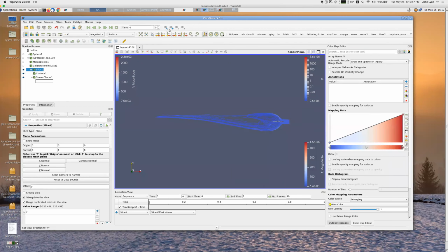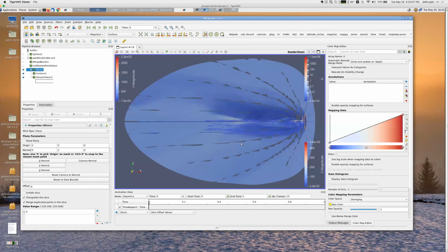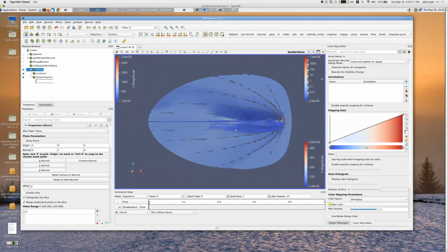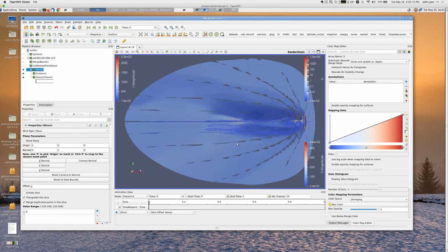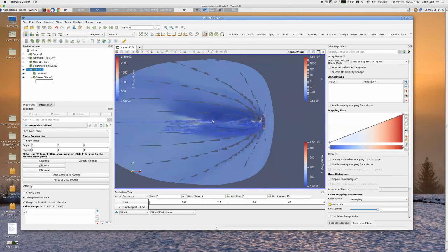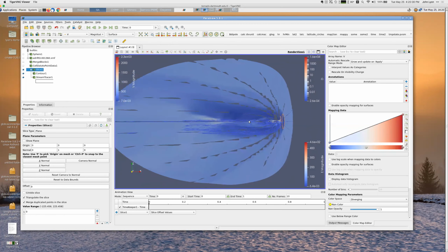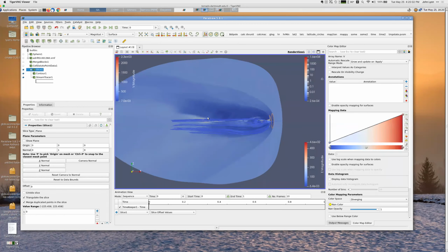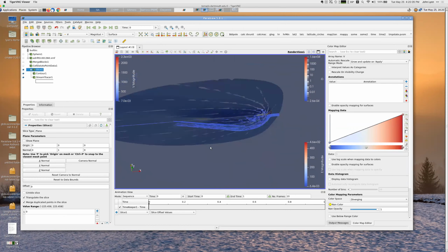And then, of course, up here, this is the default view, so I can change it now to look from the Y direction. And you can move, you can increase the size of your thing. Typically, this is the right mouse button on a three button mouse. You can move it side to side, like so. That's the middle button. And the first button usually is just to rotate the object.